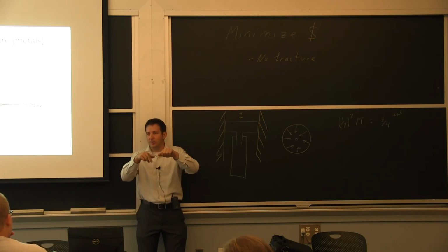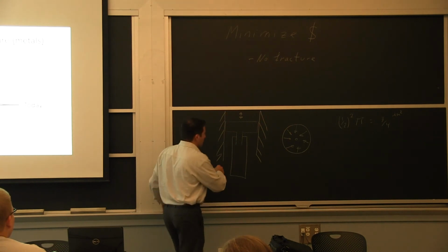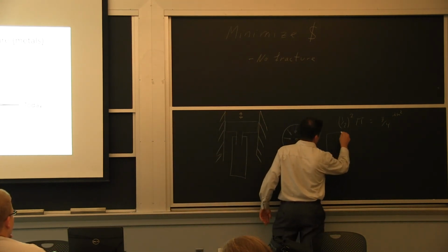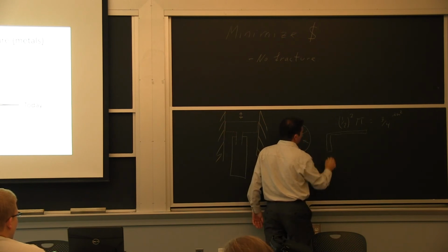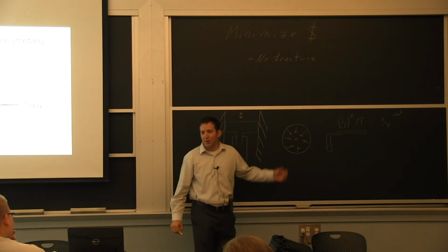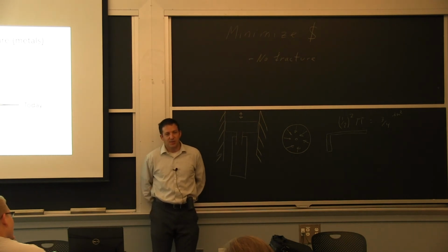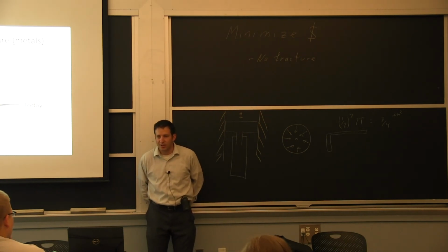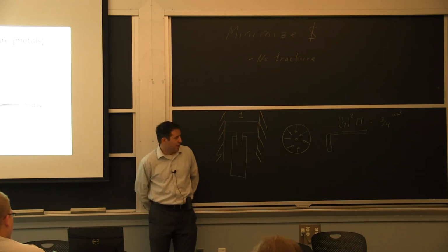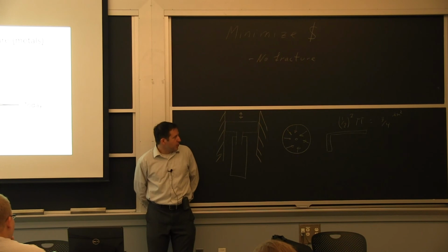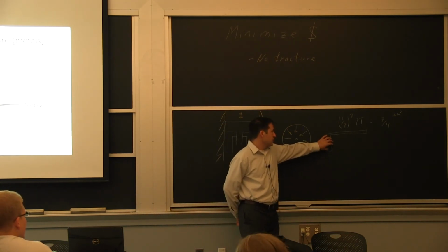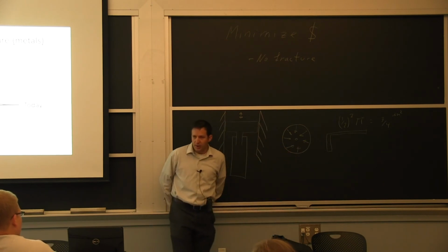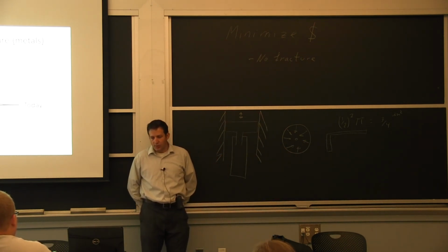I've seen that in some failure analysis. You have the size marker, it's a 1/4 inch on the, if you get a little Allen key like this. So right here, if they put a size marker where you have the highest load, the crack starts right there, because you have stress concentration, and it's essentially a brittle material even though it's steel at ambient temperature. So we want to tie in what makes the difference. Why is this one brittle as opposed to being very ductile? That's the goal of today's class.